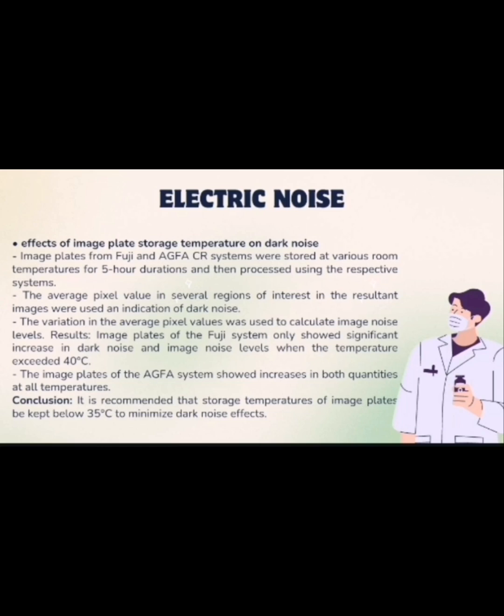Result: image plates of the Fuji system only showed significant increase in dark noise and image noise levels when the temperature exceeded 40 degrees Celsius. This approach can help identify areas with higher levels of dark noise, which could be important for image quality assessment or noise reduction techniques. The image plates of the AGFA system showed increase in both quantities at all temperatures. Conclusion: it is recommended that storage temperatures of image plates be kept below 35 degrees Celsius to minimize dark noise effects.